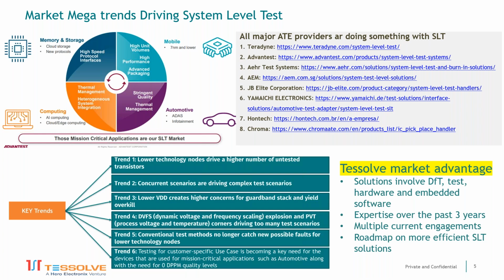So, Mike, that leads to the logical question: when you've got 10 chiplets in a package and no chiplet has been tested fully, how is that going to get tested? Well, that's a good question, because we had the known good die presentation before. I don't know if you attended that. Basically we were saying that a good flow for chiplets is to make sure you've tested those die before they go into the chiplet package and you've assembled them.